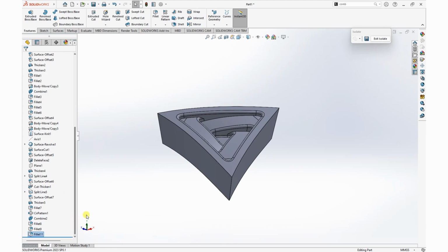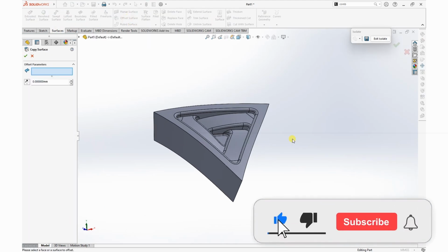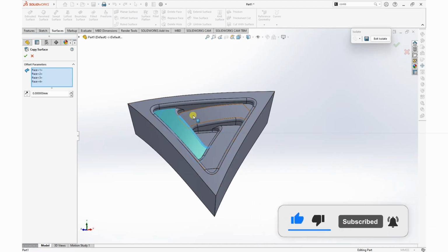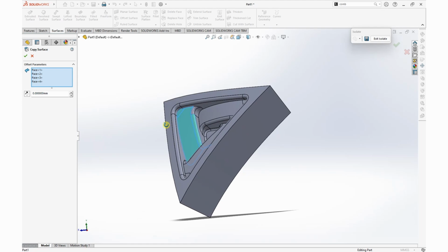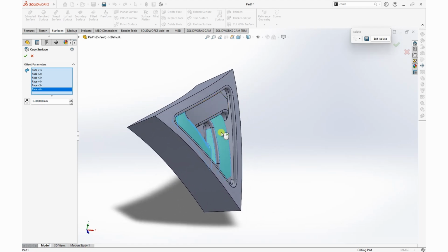So again, now here you have to offset the tangency. Select tangency. The selection is not great there, but you can do it manually. If you could have gotten the fillets right, then the selection will be just automatic as the previous one.